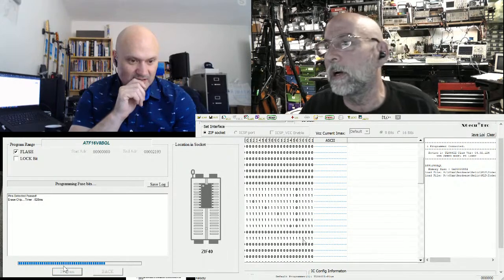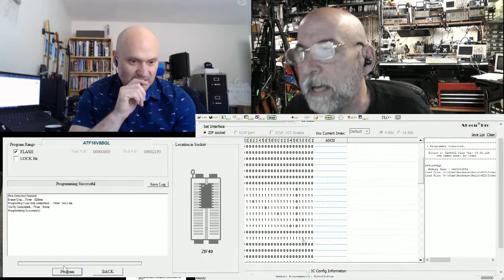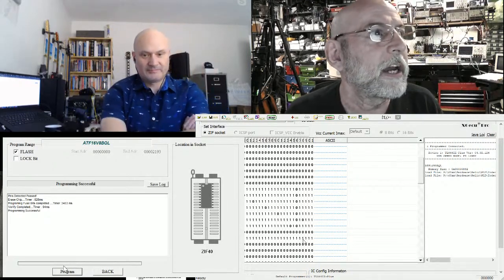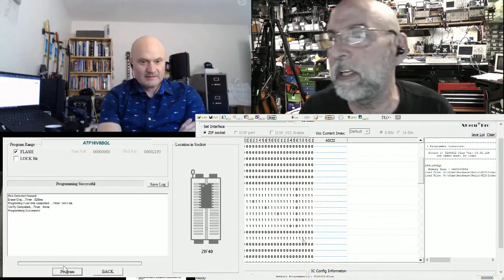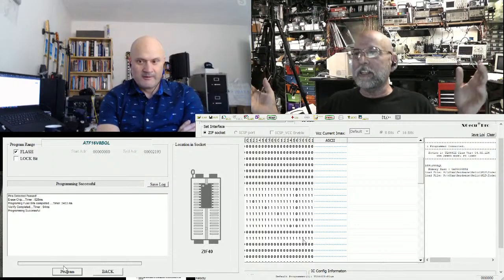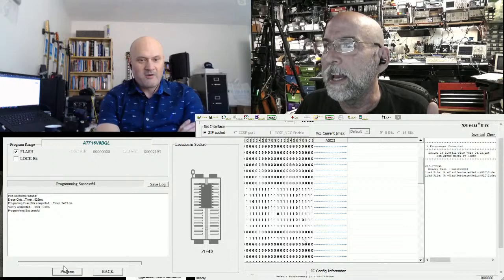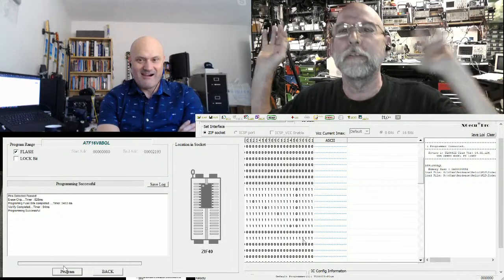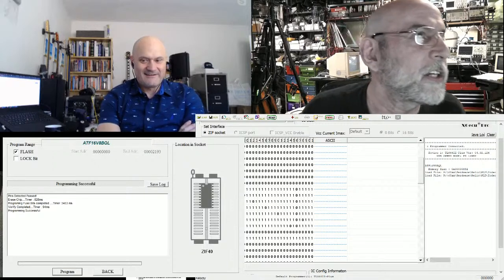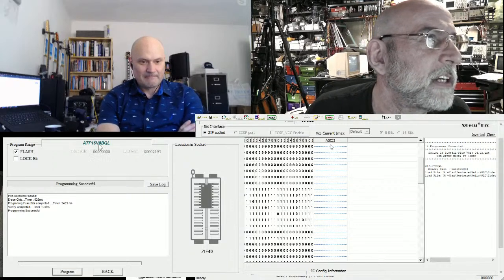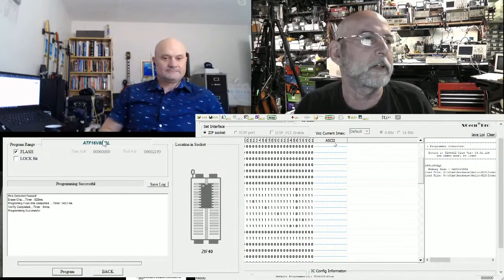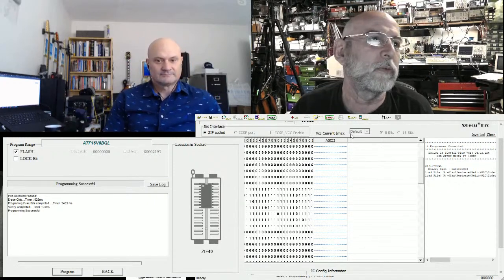And it actually works. And that to me was amazing. Now, I had chosen the wrong part originally. I had chosen an ATF16V8C. I was just being lazy. I said, it's a 16V8, it'll work. And it got halfway through and said, nope, I blew it. I researched it and I chose the right device, ATF16V8BQL, which is the actual device, and then it worked. So you can't be sloppy about which part you put.